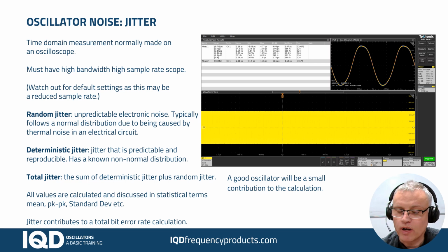And what I have learned from this is that you need to be careful when you adjust any setting on the oscilloscope. Very often the bandwidth jumps back to some default value, and you have to manually turn the sample rate back up to the maximum. So just a little tip there when you're playing with this equipment. We found that to be the case in most of our scopes.